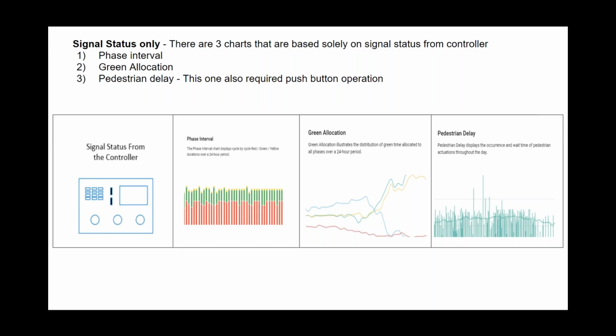And these just generally come from any traffic controller. We often collect it through NTCIP, the Ethernet connection. It also can come from SDLC as well if you're only connected over the one source, but it really helps you assess how well it is operating without detection inputs.